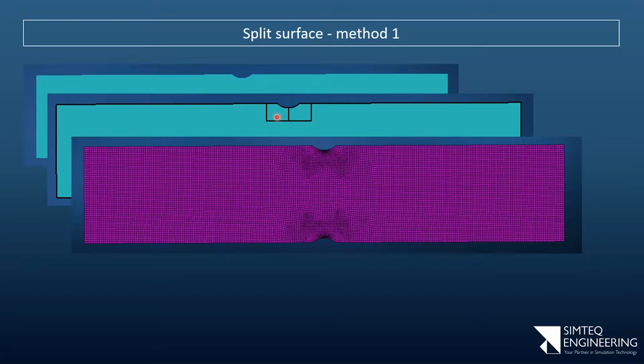And by doing that, I can specify different meshes on these. I can even, in this case, it's not that clear there, but you can see the mesh density towards the center is higher than towards the ends. So mesh seed with a fine mesh, but going to even finer in that location.